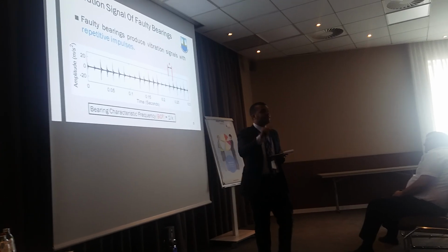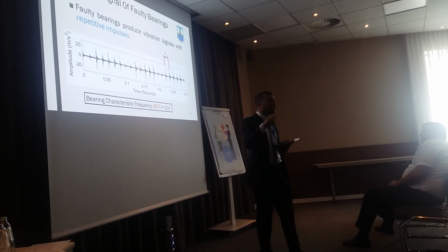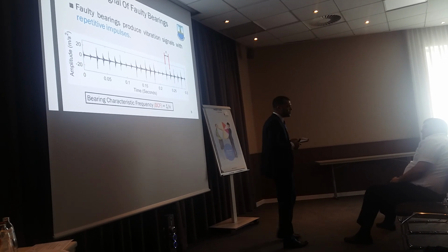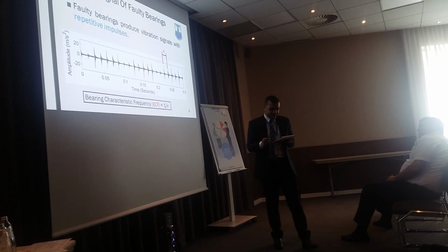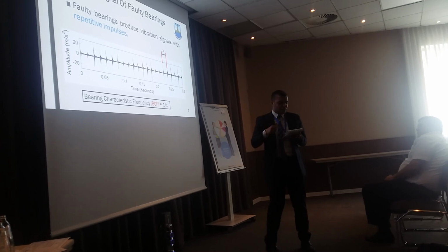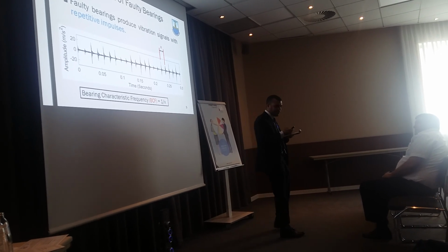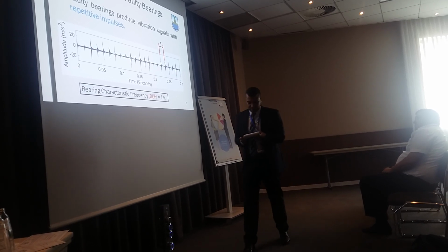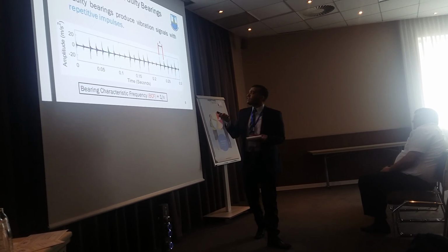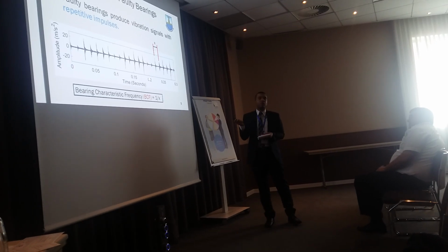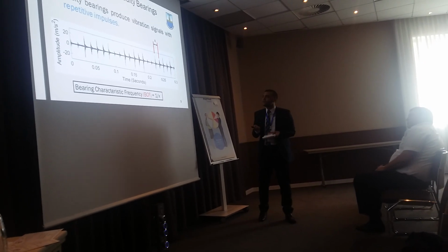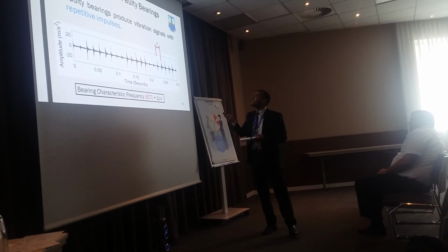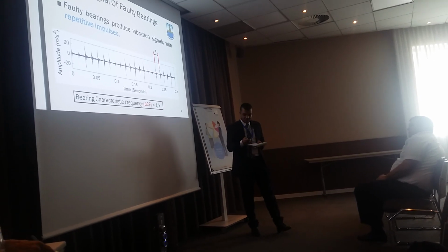Bearing faults usually start as a local fault. During shaft rotation, every time this fault strikes the mating surface, an impact is produced, which appears in the vibration signal as an impulse. As the rotation continues, an impulse train is produced in the time domain of the vibration signal, which is the characteristic shape of incipient bearing faults, or small bearing faults. The reciprocal of the time interval between two consecutive impulses is called the bearing characteristic frequency.